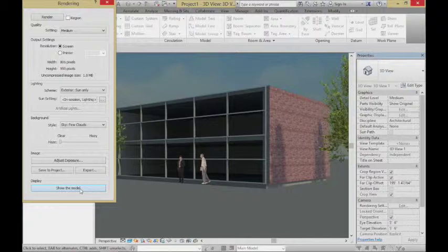Where we left that discussion was really on the notion that we tended to size these systems based on just the amount of air we needed to move through a room. For every room, based on the type of use of the room, there was some notion of how many air changes per hour you needed. So in a room like this, we might need to move 2,000 cubic feet per minute, based on the number of air changes per hour.